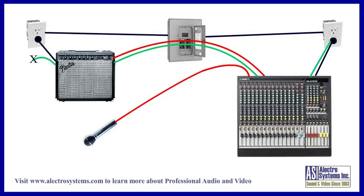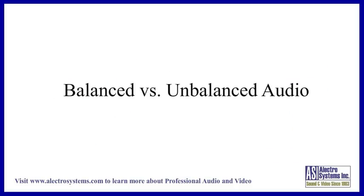The proper solution is therefore to break the ground connection between the two devices, in this case the guitar amplifier and the mixer. Hang on to that thought, because at this point we're going to take an important sidetrack. We're going to talk about balanced and unbalanced audio systems.